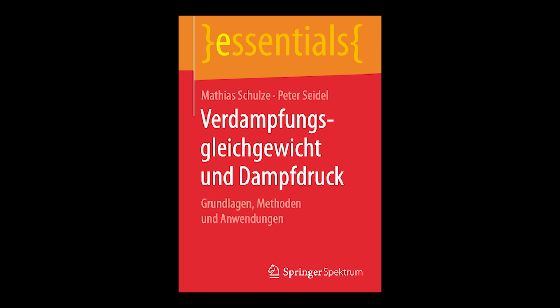Exactly. It enters this unique fluid state called a supercritical fluid. For water, this happens at a staggering 22 megapascals. Wow, that's about 220 times atmospheric pressure. It is. And 647 Kelvin, or 374 Celsius. The key physical concept is that above that critical temperature, you can apply infinite pressure, but the substance will never condense back into a recognizable liquid.